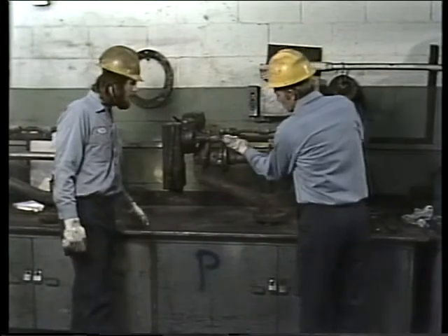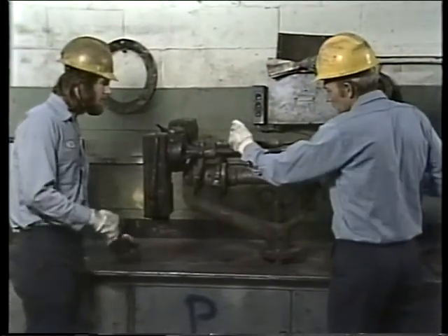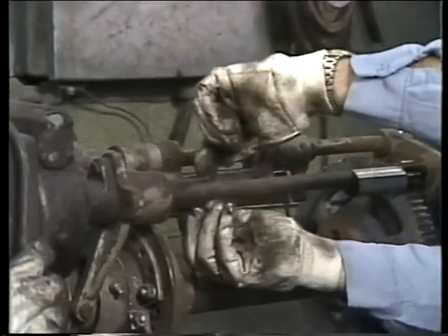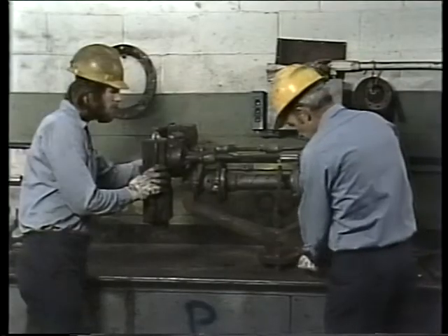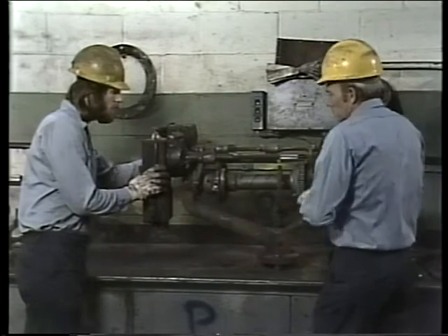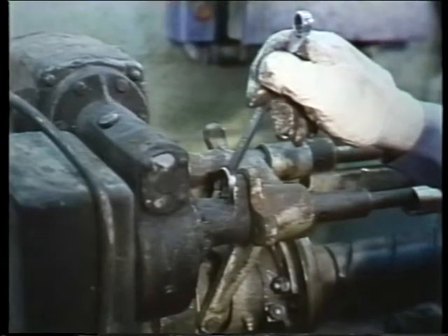The metal collar covers a scroll pin that holds the shaft to the output of the motor drive speed reducer. The pin is removed easily with a hammer and a drift. The motor can be loosened and pulled out, and the drive shaft is free also.